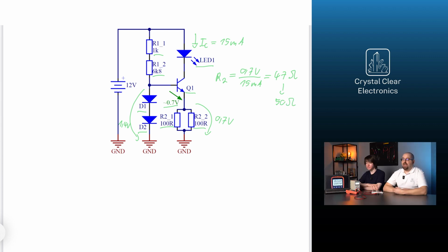The next step is to define the resistance R1. First, find the transistor's current gain in the datasheet. This is at least 200 in case of the BC546BTA, so to get a collector current of 15 mA, the base current must be 15 mA divided by 200, or about 0.07 mA. The diodes need an additional 1.3 mA to produce the expected voltage drop accurately, at least according to their datasheet.